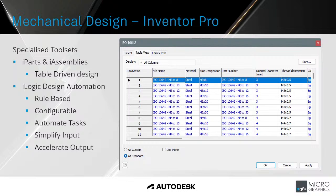So here on the right-hand side, a very simple bolt that I pulled from Content Center, which is essentially an iPart. And we have all the different columns within the table that give us our sizing for this bolt. And so once a component is set up with its different configurations in the table, all you need to do is choose the configuration and insert that into your assembly. So you choose which row you want. If I want an M4x10 bolt, I go down to row 9 and insert that row. I don't have to draw that bolt from scratch.